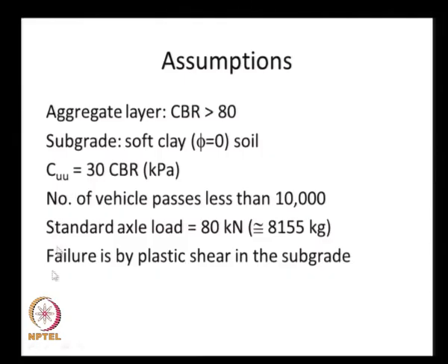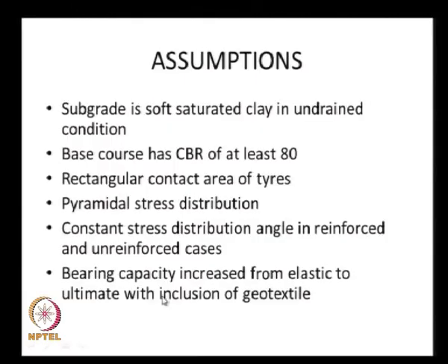The number of vehicle passes is less than 10,000 passes, and a standard axle load of 80 kilonewtons is considered. 80 kilonewtons is approximately 8,155 kgs, which is equivalent to our IRC standard axle load, and the failure is only by plastic shear happening within the subgrade soil.